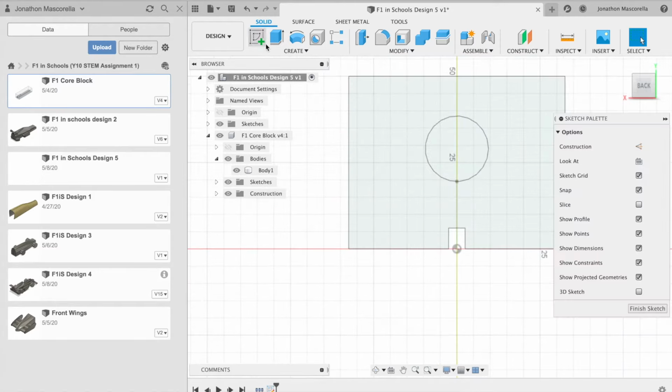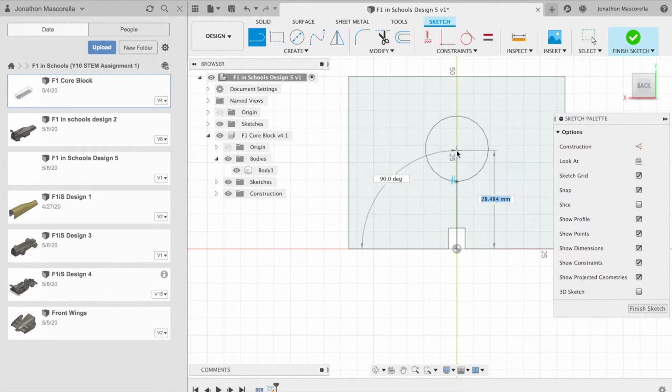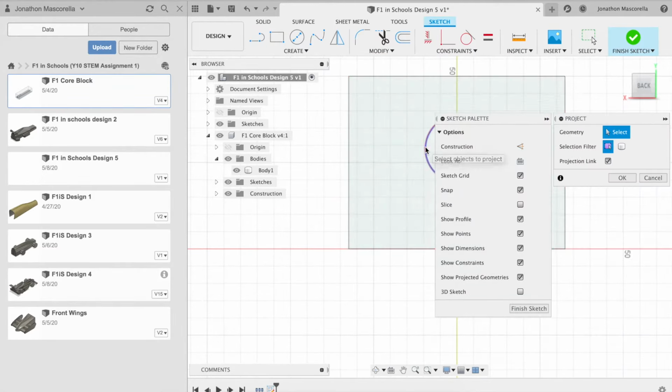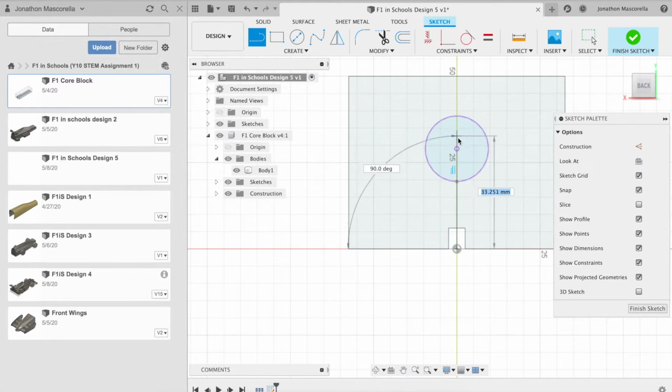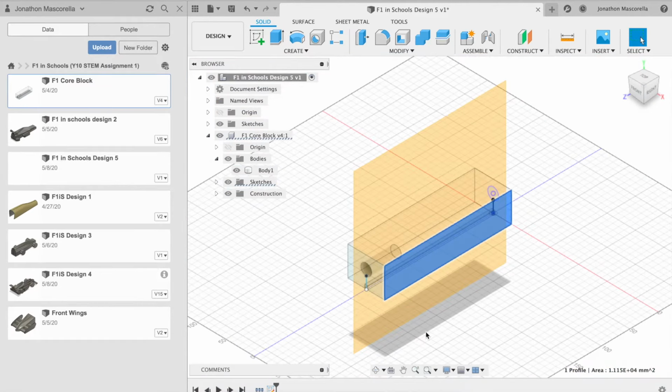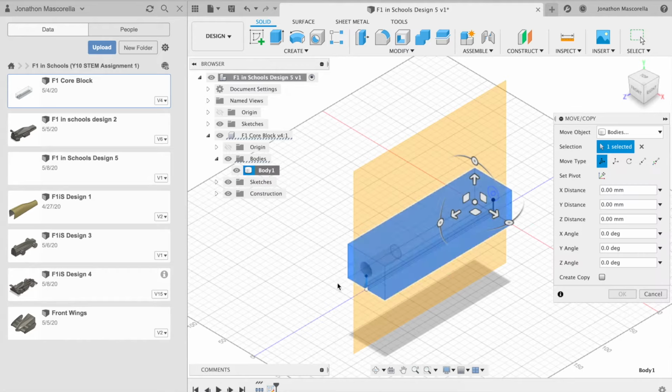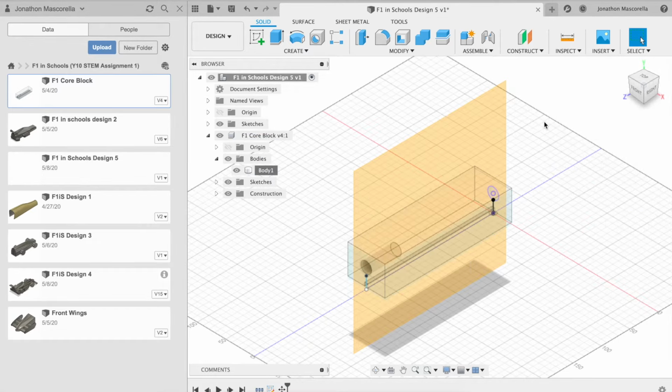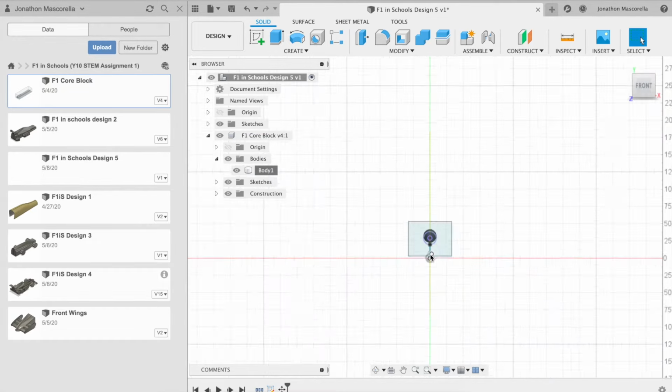a guide, and moving into the center of the plane just to make sure that we know exactly where it is. Now we're going to be measuring the distance from the bottom of the CO2 canister here to the deck, and it's 19.5 millimeters at this point. So we need to actually move it up a little bit, and that's because the minimum specification from the bottom of the CO2 canister to the track is 22 millimeters. So let's just move that up 3.5 millimeters,